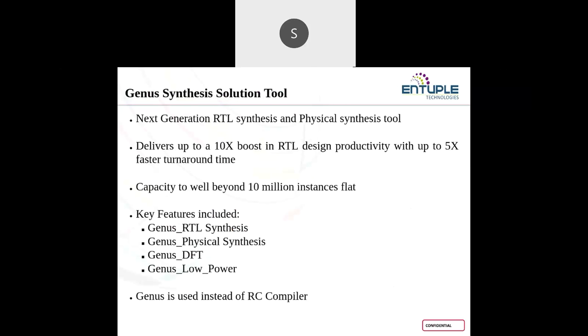required for the synthesis process. First one is the RTL code, the timing constraints, or you can say predefined constraints, and along with that I am making use of the technology library, that is a .lib. You also have the option to set a .lef. LEF means library exchange format, which includes the complete physical information. When you are going with physical synthesis, at that time you need to give the .lef file, but with logical synthesis, the .lef file is optional.